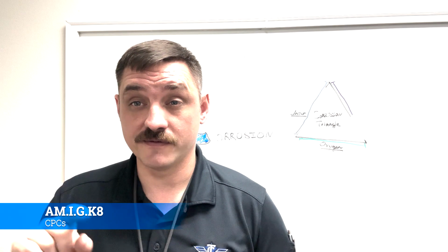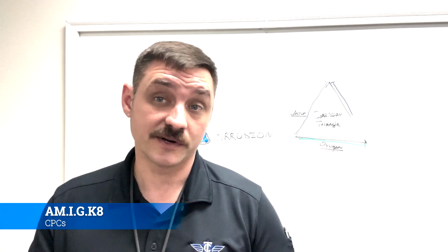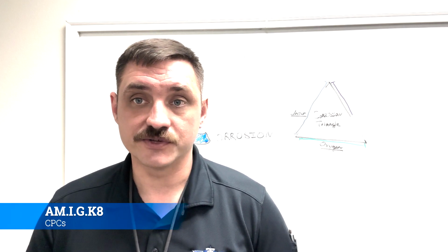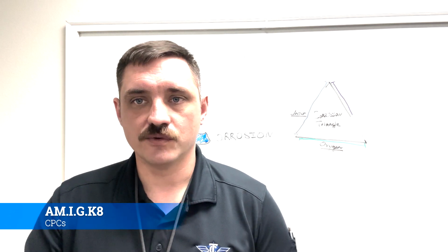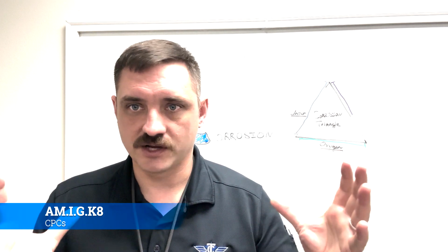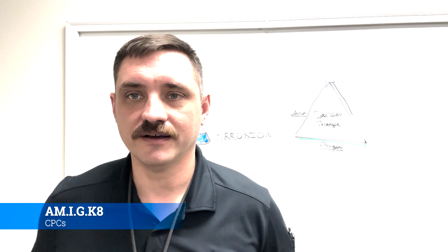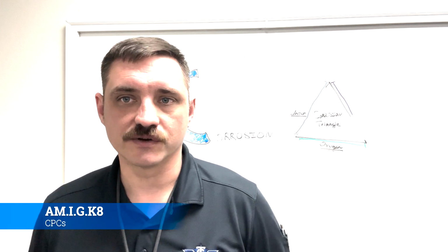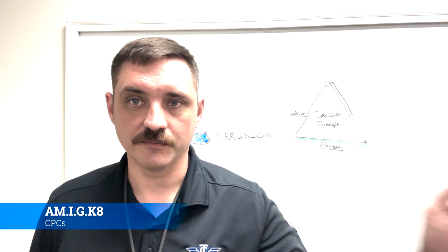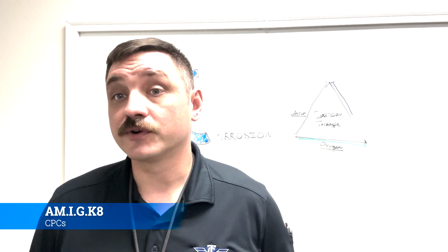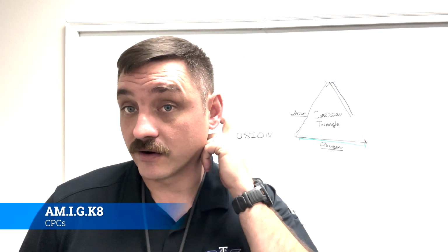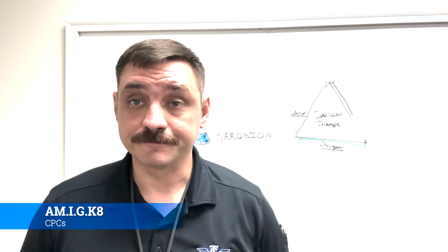So you'll take note of it if there's a scratch or it's been removed or whatever, because that opens up that part to corrosion. But if it's all encompassed in that film, then you generally don't have to worry about it. You just kind of GVI it and move on. Other types of CPCs that are out there and available on the market.